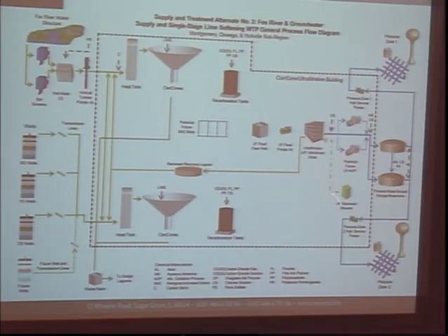The back end has the most current technology relative to filtration. For a Fox River water treatment plant for the village of Montgomery on its own, you can actually use the filters that are there. They have to be modified some based on the media. If we were to put in a new sub-regional treatment plant, the filters would be slightly different. After treatment, the water would be stored, and then you'd have to pump all of that treated water from that treatment plant location to each one of the communities, and we're going to show you in a second schematically how that works.